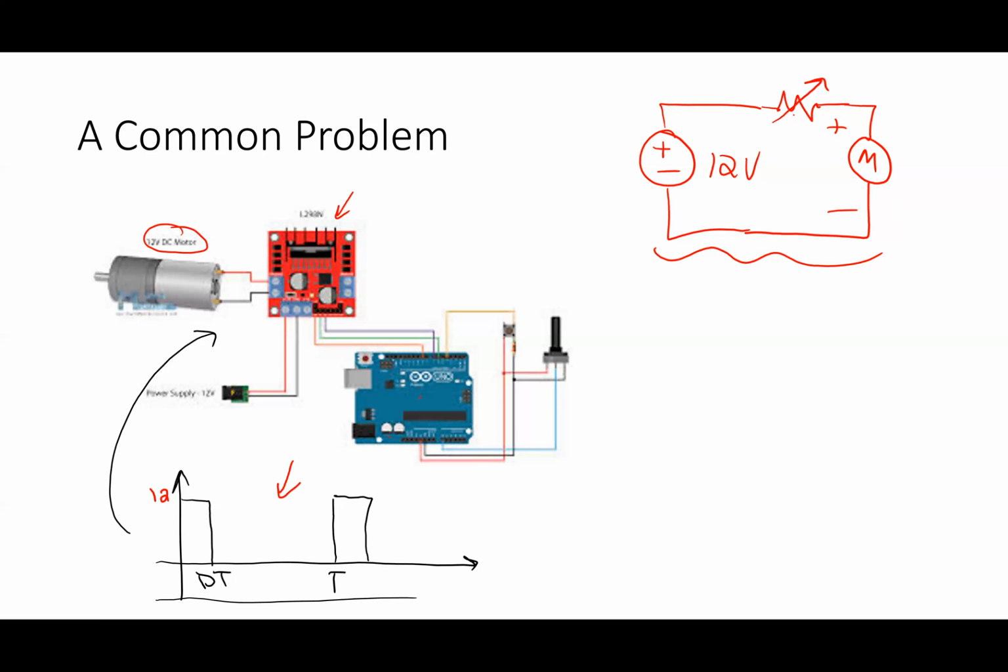If I have a resistor here, what happens if I have current flowing through a resistor? It dissipates heat, right? And if I want to go really slow, it's going to dissipate a lot of heat. So this resistor works quite well. It makes a variable supply for me, but it's not a very efficient way to do it. There's an almost 100% efficient way to do it, which is the picture that I've got here.